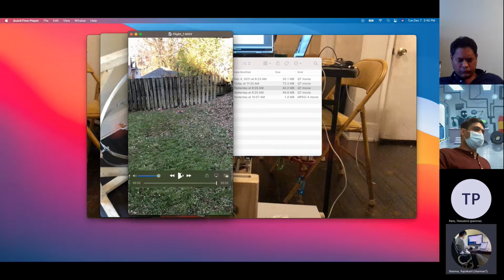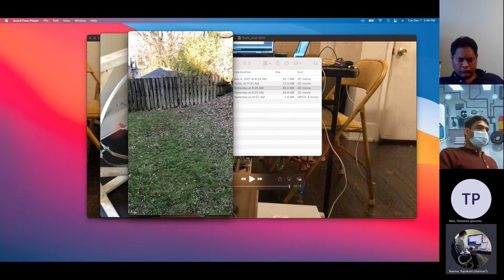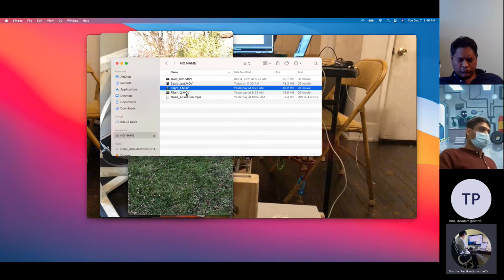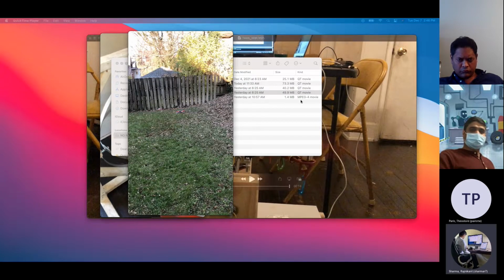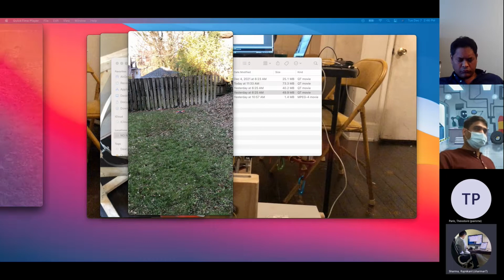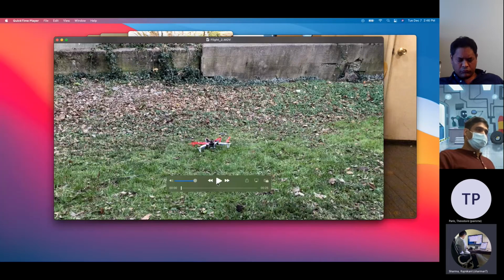So how do you know what it is doing? Like, did you plot this? Since we were just able to transmit commands to it, we don't have the actual data for in flight. From the test on the setups, we were able to record data. Those were the plots you saw. I was just trying to keep it in the air. So basically, we were just commanding phi and theta, your pitch and your roll, manually transmitted. Since it only has an attitude controller and no position controller, if there's any angular error, it'll start drifting. So you have to constantly correct it and try to keep it in one spot.